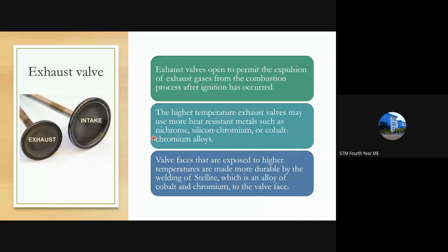If heat resistant metals are not added in the exhaust valve, failure of the exhaust valve will occur and the sealing action of the combustion chamber will be lost. For that purpose, we are using heat resistant metals in the exhaust valve.